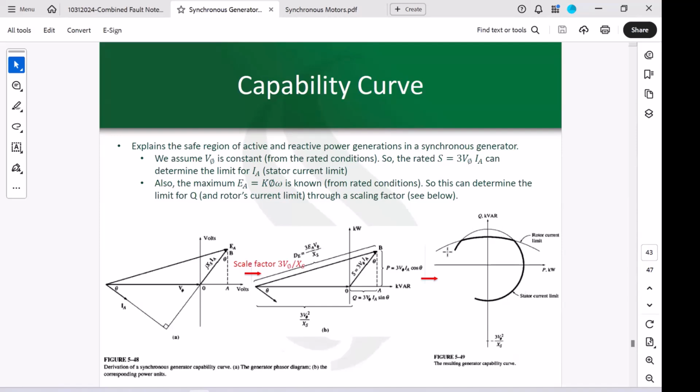associated with your generator that is in general associated with the S, or the apparent power. So each of the points on this circle shows one P and one Q, right? If you go here, there's one P and one Q. So overall, you should always be under the areas that have been intersected with these. So this is a good operating point.